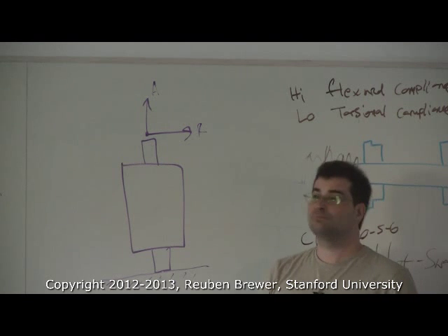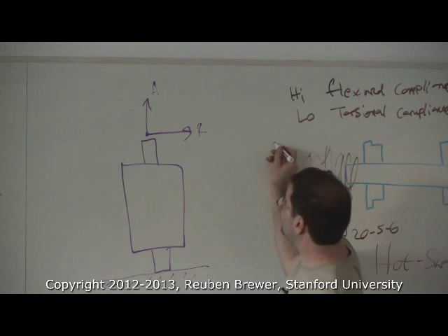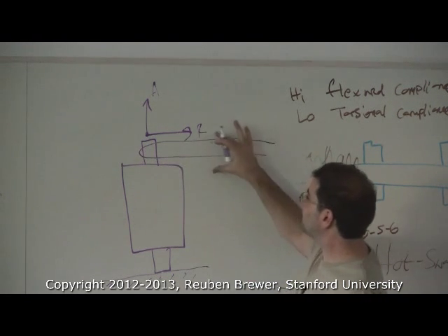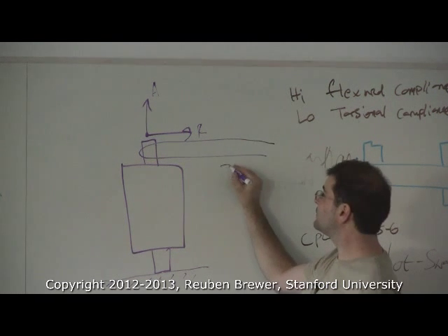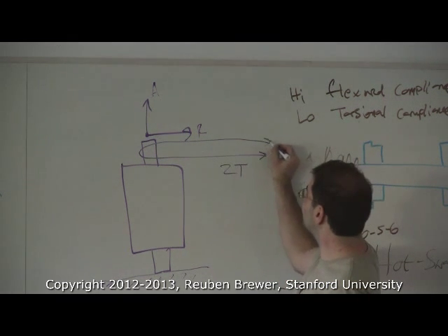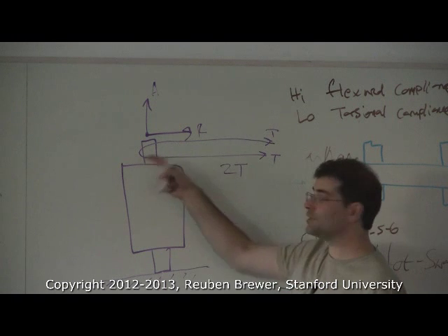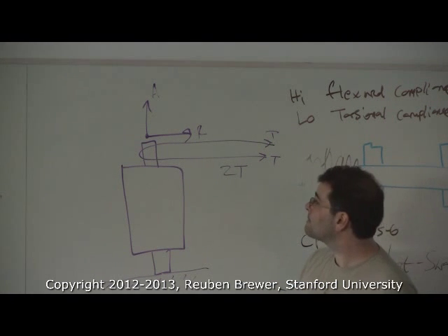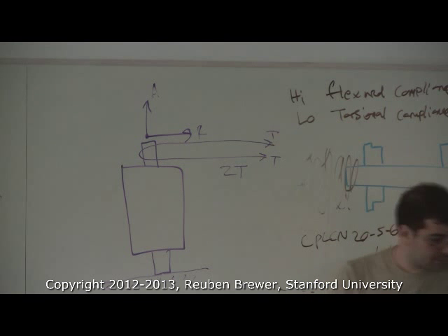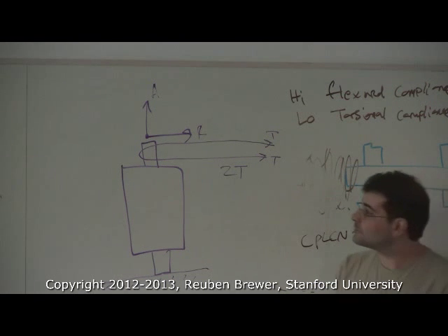Let's talk about the radial load. Lab 2, belts. Belts are terrible for radial loading. So we tie a belt around here and we yank, and we have twice the tension on the belt, right? Tension, tension, 2 tension here. Now notice it specified max radial loading 5 millimeters from the flange.